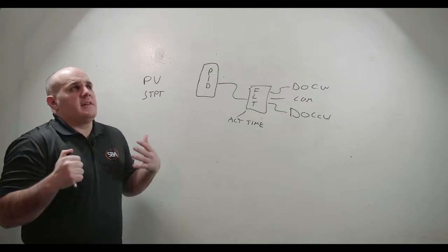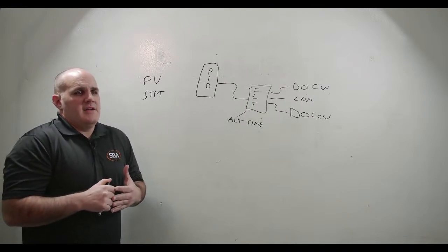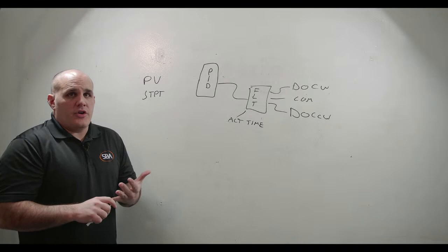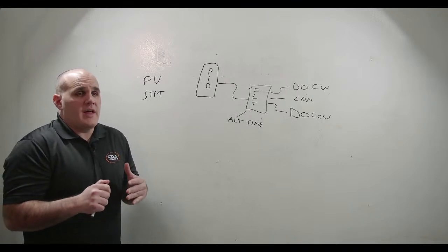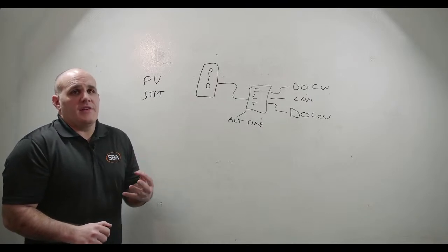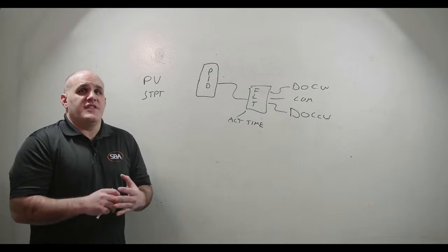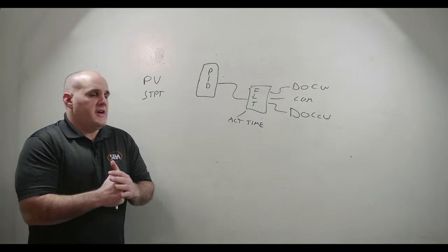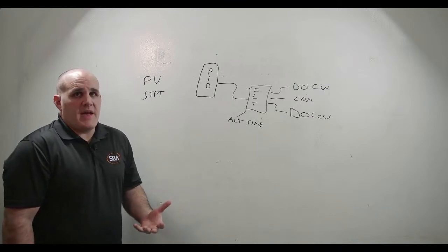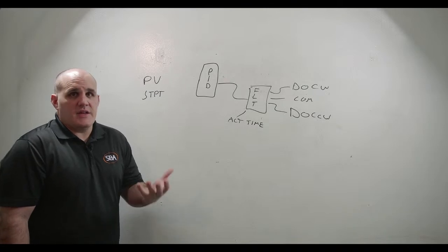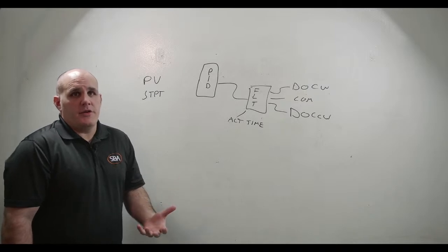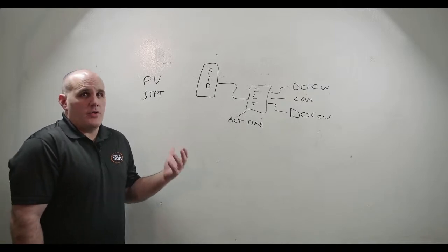I feel like from a controls perspective, a lot of folks focus on things that are overly complex. If you just get on-off control, PID loop control, floating control, and sequenced control down, those four, you will be able to handle almost 90% of the things you're going to experience out in the field. On-off control is going to be your fan commands and your electric heat commands. Sequenced control is going to be like sequencing up chillers, sequencing heat, etc. Floating is going to be for your terminal units and fan coil units where you're using hydronic heat and you want a low-cost actuator.